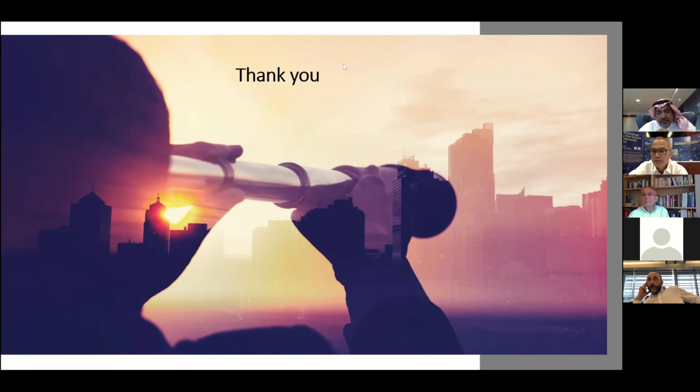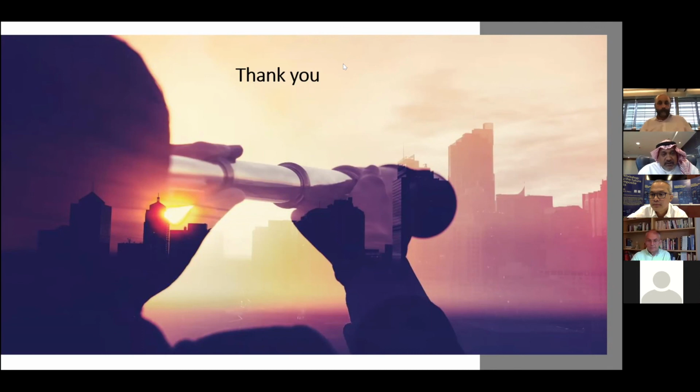How you design the part, how you bag the part, and how you do something called tacking. When you start doing the first layer and the second layer, we do something called tacking. You tack the material together. You try to compress the material together to make sure there's no air bubble or gaps in between the two layers of material. So it's not a resin infusion we're talking about with these machines or the hand layup. It's more of the thermoset, not a dry fabric.